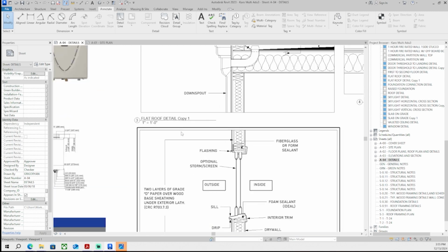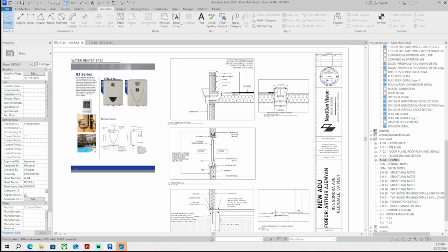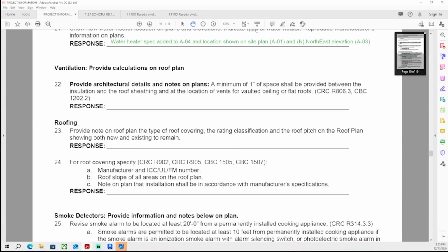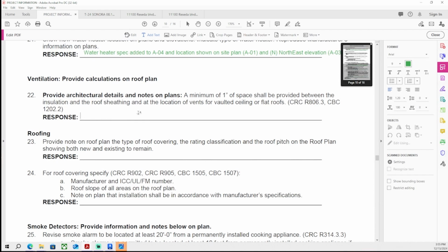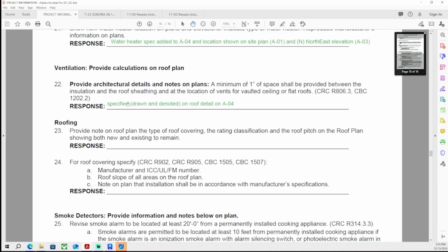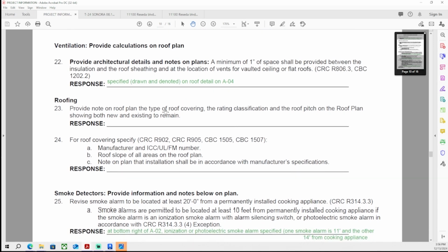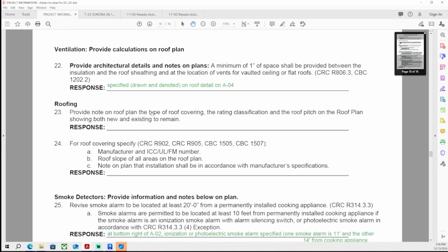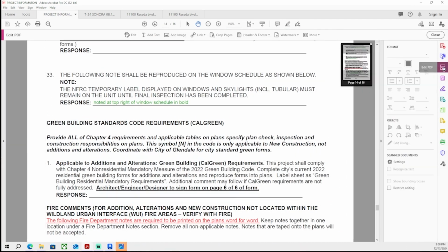but you do get more R value with less thickness. The way insulation works is it's really on the thickness. So you'll see on the walls you've got R15 insulation and it's thinner. On the roof you've got R30 insulation, it's thicker. On the flooring you've got R19 insulation, a little thicker than the wall insulation, but not quite as thick as the roof insulation.